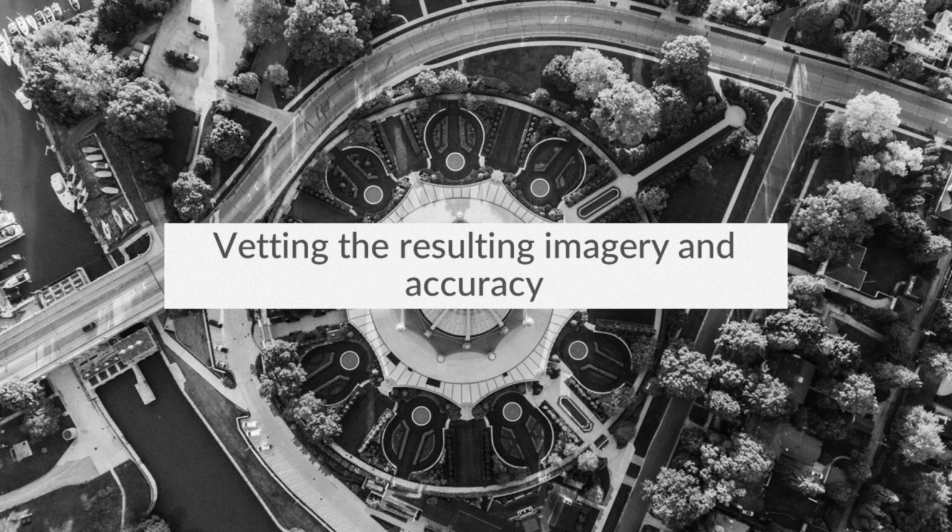And then do you typically have control in these locations, or are you just using prior iterations of the mapping to kind of register the data sets? Well, we do use ground control. A lot of the sites, you request the mine to put in permanent ground control points, which enables quite easily the multi-temporal analysis. But we also have a couple of sets of aero points which we take out as well, which are the portable ground control points, with GPS built into them.